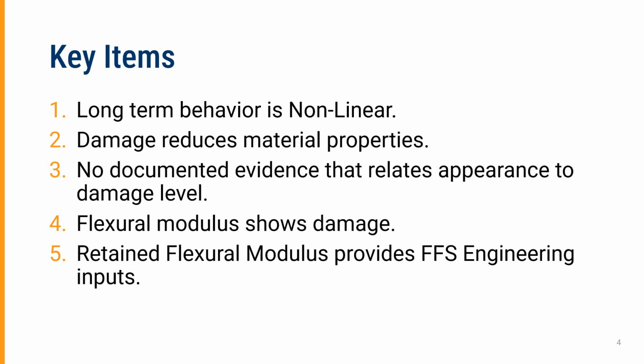The key items to discuss and understand regarding damage mechanism for FRP are listed here. First, long-term behavior is nonlinear. Second, damage reduces material properties. We actually have a change in the physical properties of the material as a result of damage.